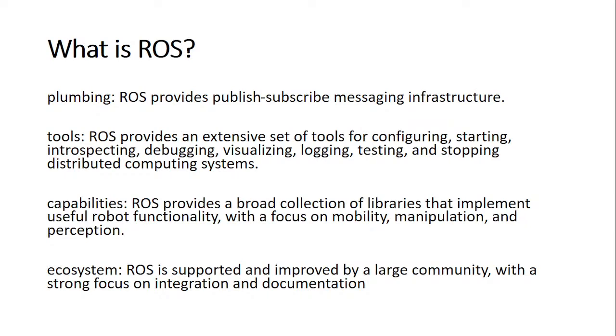We can use a single board computer for that. So the velocity vector values should be sent from the ROS single board computer to the microcontroller. So this is a messaging system. Here ROS uses the publish and subscribe model. Publish and subscribe means the microcontroller will subscribe to a particular topic. It has the same sense as